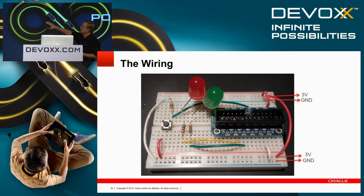And then in the middle section, you've got 5 rows horizontally: A, B, C, D, and E, and those are connected vertically, right? So each 5 are connected vertically in that block, and then in the bottom block, F, G, H, I, J, those are connected vertically as well. And so in that manner, for example, that red wire on the left is actually connected to the bottom part of that switch. When you close that switch, then the upper right-hand corner of that switch, the electricity is going to go through that resistor to ground. So that's how our breadboard works.